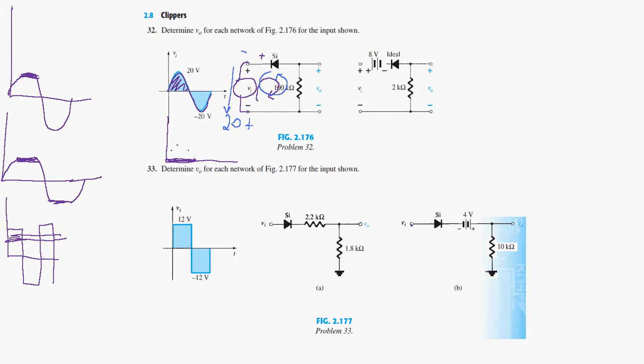And so here we have just a positive voltage, 20 volts in the counterclockwise direction here. So this 20 volts will appear here, and because of the 0.7 volt drop on the diodes, the voltage here will be 19.3, sorry, after the diode drop.